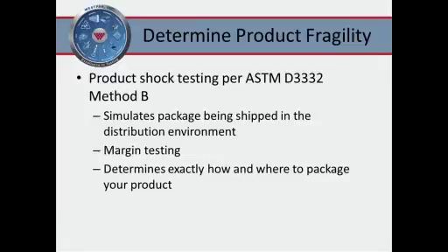Anyway, many people take shortcuts with it because of the lack of product available for potentially destructive testing. But the important thing is that walking out of a damage boundary test, you have a lot of information about exactly where and how the product breaks. Over the past way too many years that I've been doing this kind of work, I've been absolutely amazed at what fails and how, and also what people do about it. There are many examples of relatively fragile products during initial testing, but if a designer or someone who has responsibility for it is there, increasing the ruggedness of a product substantially, in some cases double, just results from another screw in the bracket or a bigger screw.